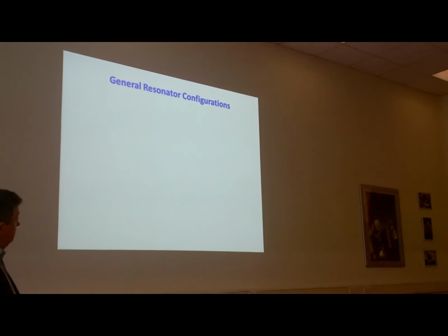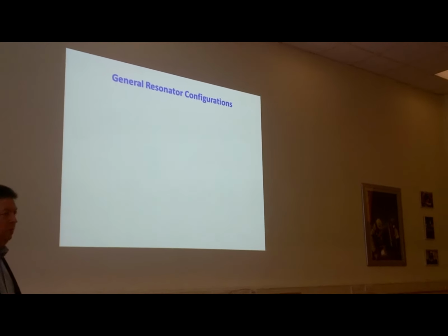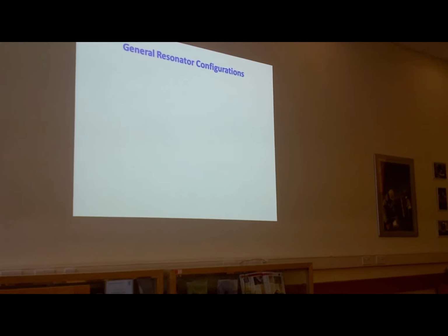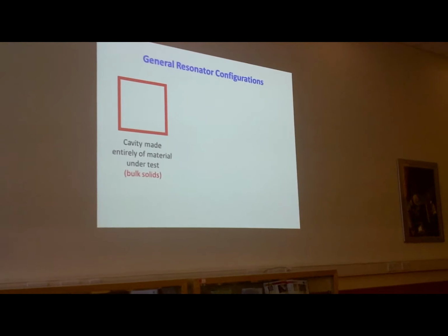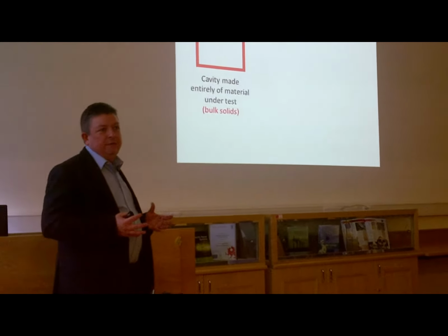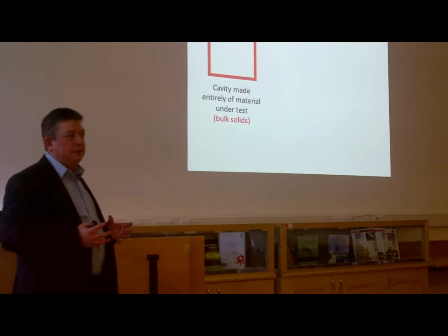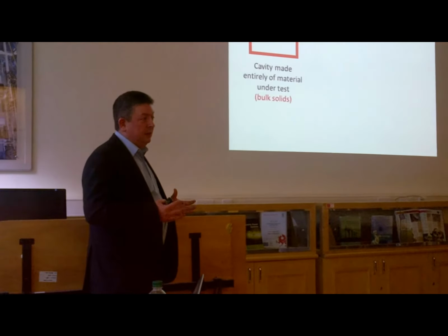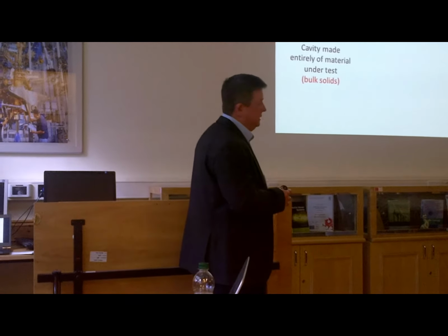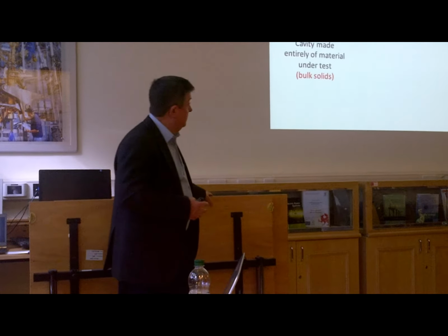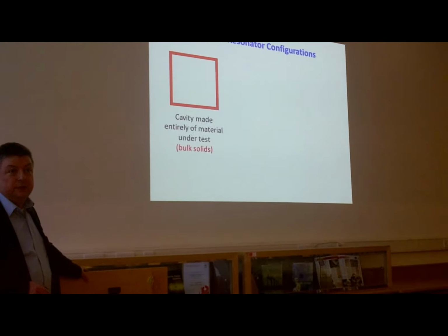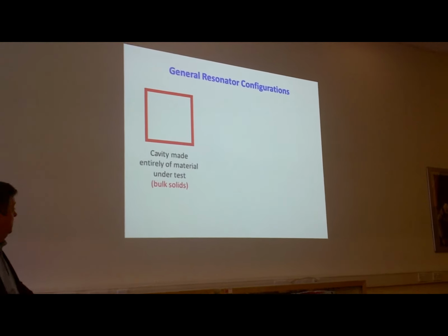So what are the sort of things that we're interested in doing then? In all the time I've been working with microwaves, I think I've measured all phases of matter, all types of samples really, because if you've got a solid material and you want to know its properties, then you can make a cavity out of that material. A typical example there would be a piece of superconductor. We've taken, for example, metals which go superconducting and made cavities out of them, and then cooled them down, and then used the properties of the resonant cavity to work out what the superconductor is doing.